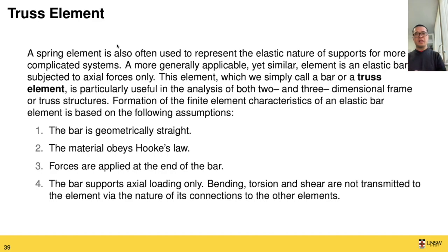spring, what you see there is we only consider the spring constant as the basic property of the element. But when you go to a realistic structure, you will have an element that has a three-dimensional shape. So the more realistic way to represent the element would be a bar structure where the bar has a finite length, has a certain cross-sectional area, and you also have some mechanical property, typically governed by its Young's modulus. Young's modulus governs how much the material will deform when it is subject to external loading.